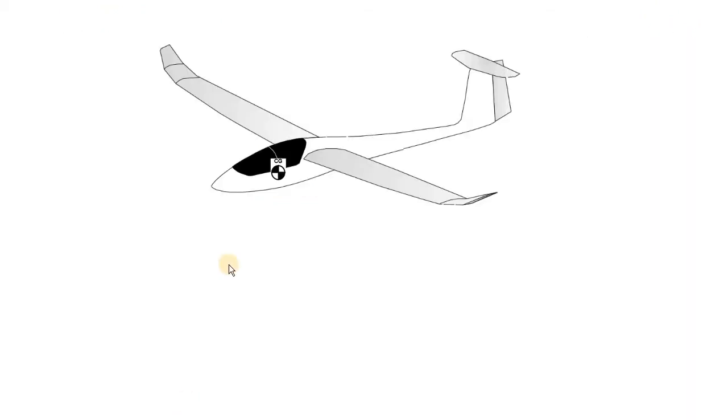And to be more concrete, let's look at this airplane. The airplane uses a standard NACA airfoil, and because of this it's not very stable. So we have to add a tail to this airplane and maybe place the center of gravity a bit in front of the wing, so that you're going to have a balanced system, this force acting upwards and force acting downwards, and then you can balance this plane. But this system is not very beautiful because it has some unnecessary parts, like for instance the tail. So let's make it better by removing this piece.